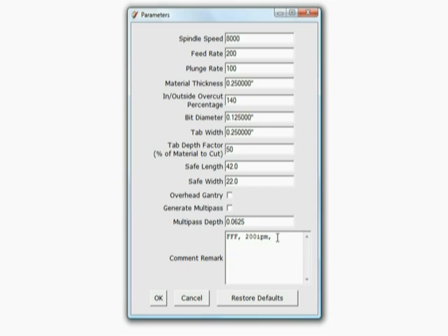This is going to put a little header in your PhlatCode file that will be visible when you view the PhlatCode in Mach 3, which is our post processor that pulls the machine code and says these are the signals I need to send to my CNC machine. That's where you might want to use these. I just generally leave it blank.